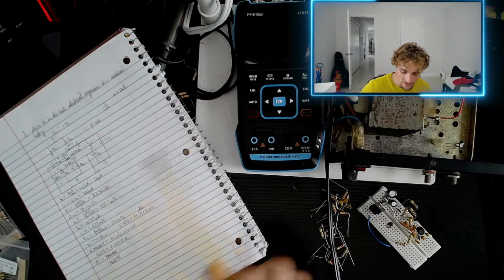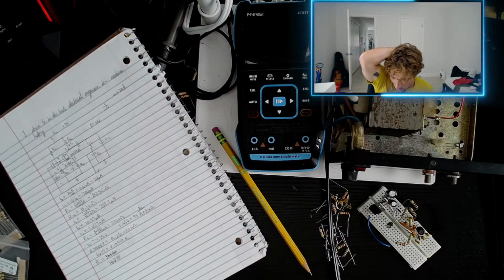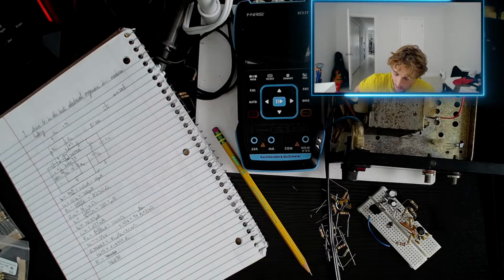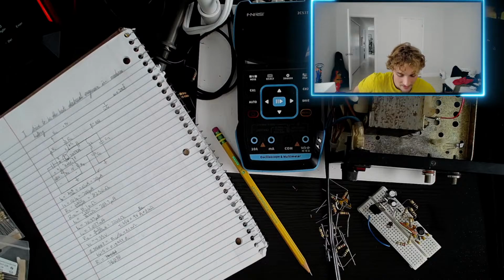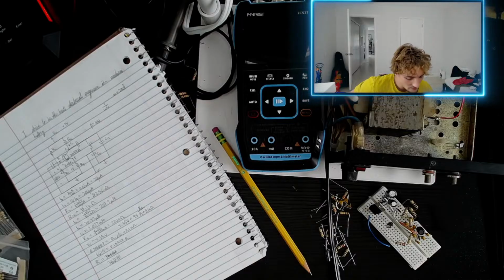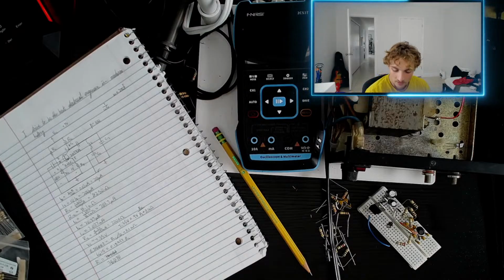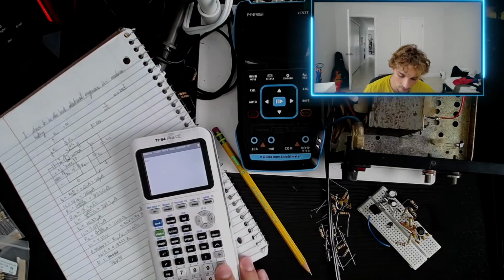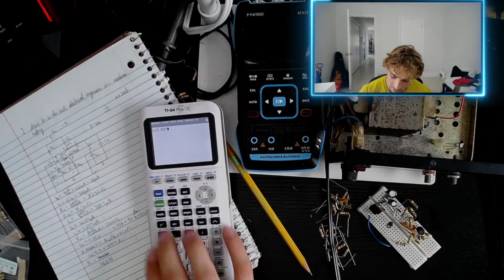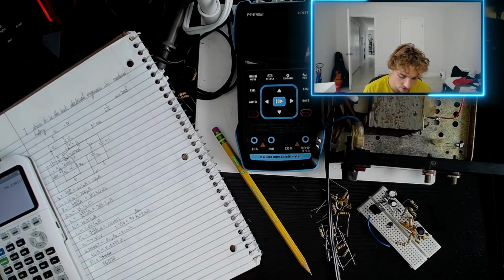Okay, our emitter resistor now. Let's see what our value for the emitter resistor will be. So our emitter current would be the addition of our collector current plus our base current, right? But our base current is 100 times less than our collector current, so perhaps we can just assume that our emitter current would be the same as our collector current. So if that's the case, we have 1 volt across our emitter resistor. Therefore, 1 volt divided by our collector current, which is 2.037 e to the negative 3, is going to give us a value of 490, which I have 470.